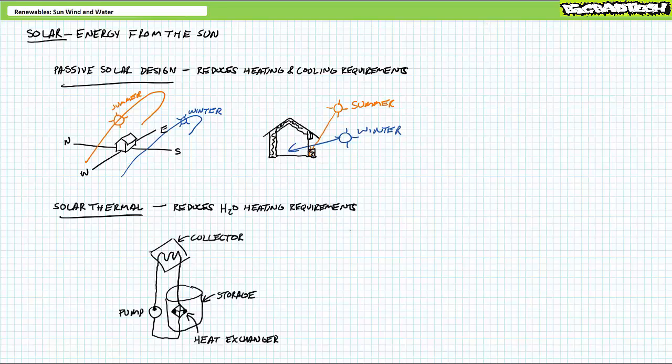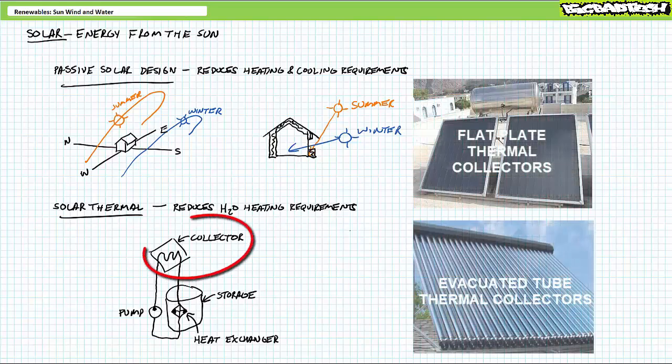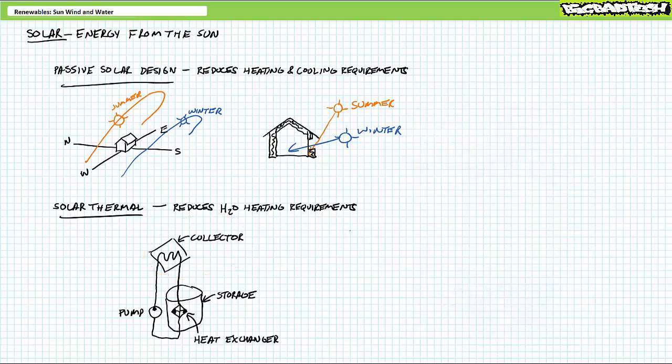Solar thermal. Solar thermal uses the sun's heat to directly heat water as opposed to an electrical intermediary. The solar collector, either an evacuated tube or a flat plate, is mounted on the roof of a structure or somewhere with good exposure to sunlight. When the collector is warm enough, a pump pushes heat transfer fluid through the collector, and the heated fluid is then routed to a heat exchanger inside a storage tank, which heats water, which can then be used for domestic purposes. Alternate configurations of solar thermal heaters, known as drain-back systems, exist that heat water directly rather than relying on a heat transfer fluid. As the name implies, when drain-back collectors are cold, the water is drained back into the storage tank, thus preventing damage to the collectors and pipes in freezing conditions.